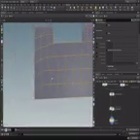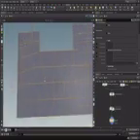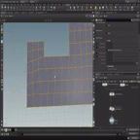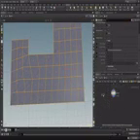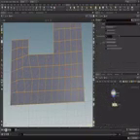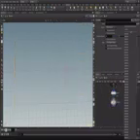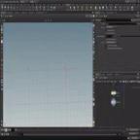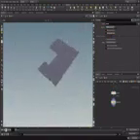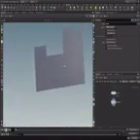These original lines were used for the subdivision, but we don't need them anymore, and we're also not selecting them because they are not cutting up the polygon and really screwing up the connectivity. That's why we can select them. So right now we can place down a dissolve node, and with this dissolve node we can remove those points. So we have a lot of pieces. We can select group 1. Don't remove inline nodes. Alright, and delete non-selected, and there we go. So now we have some nice squares, which is what we wanted.